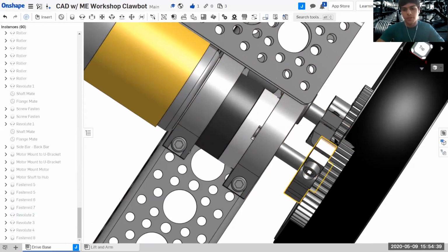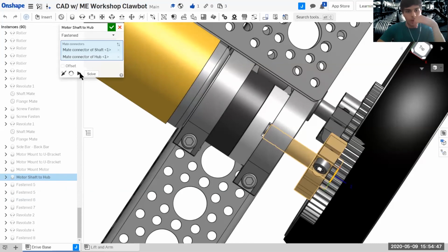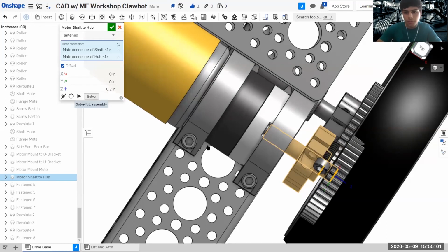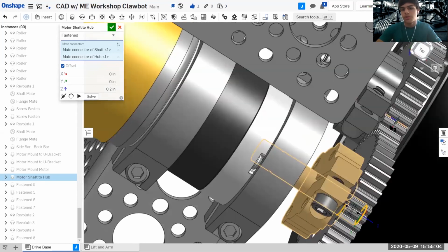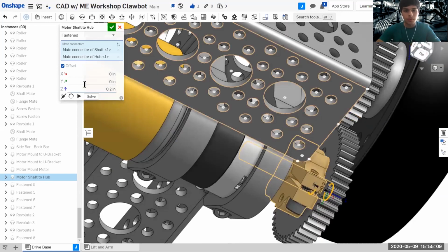I'm going to offset this so that it barely touches the wheel. So either double click or right click and edit, and then offset. I want it on my Z axis, so it's probably going to be a -1. Let's see, wrong way, so it's that way. So I'm going to just move it back a little bit, see how it does. Sometimes you have to play with these. Other times you can just measure the distances and see which is the best. So I'm almost out, maybe 0.1 more inches. Sorry, 0.1 more inches, not just 0.1 inch, if it'll load.